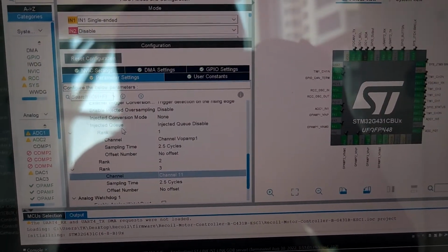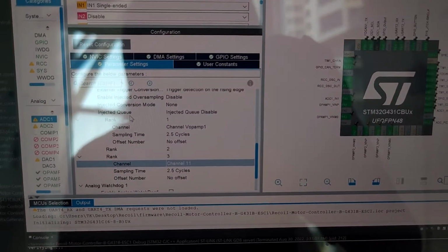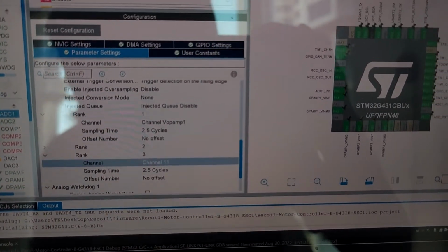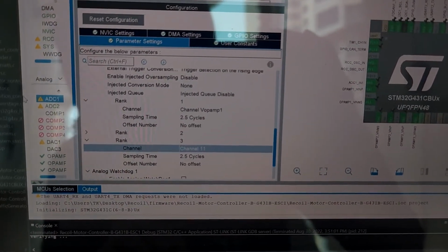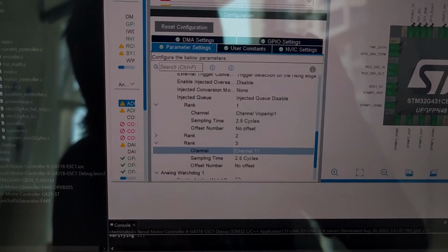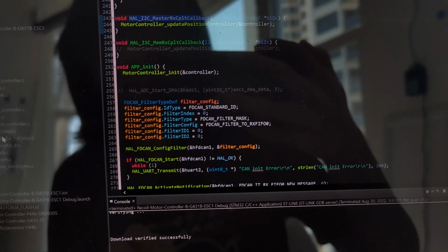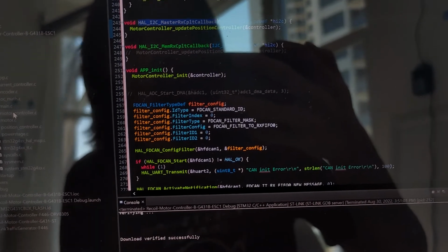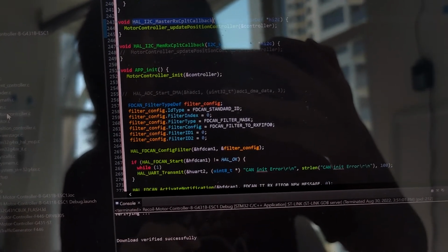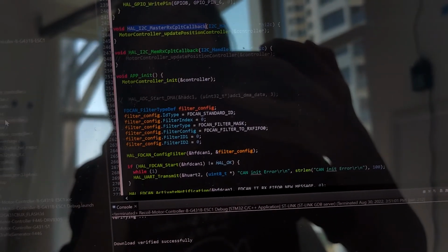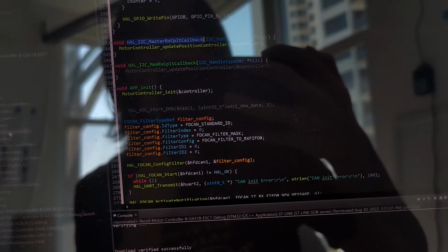Oh, and also an interesting point that comes to me now: I was using an IIR filter for the converted IQ and ID current, because they are rippling. Phase current sampling isn't precise at all, right?